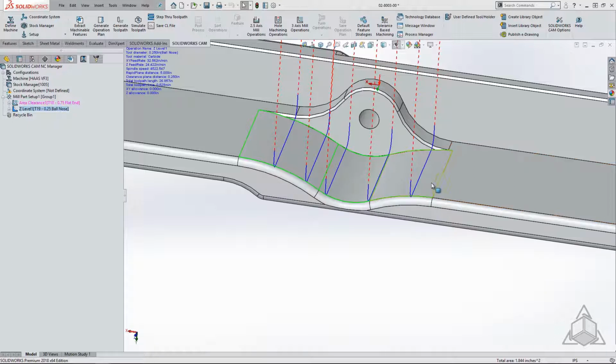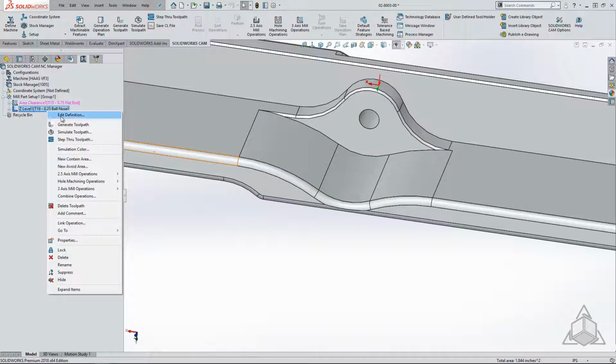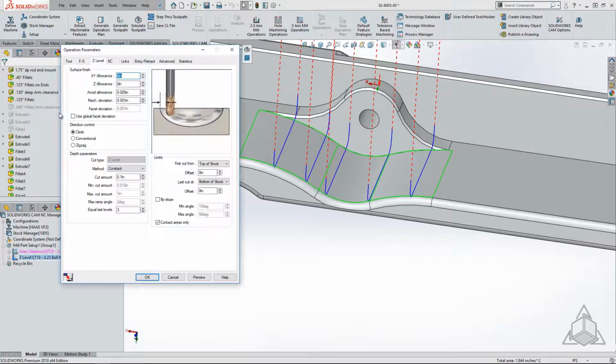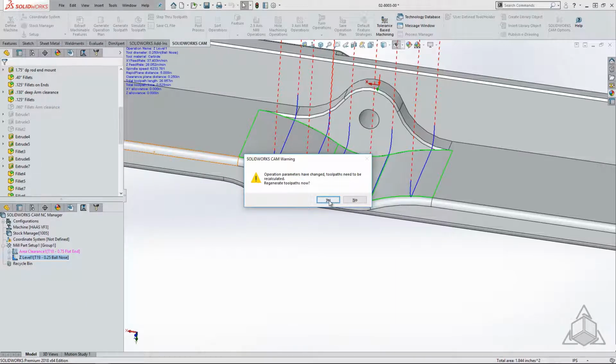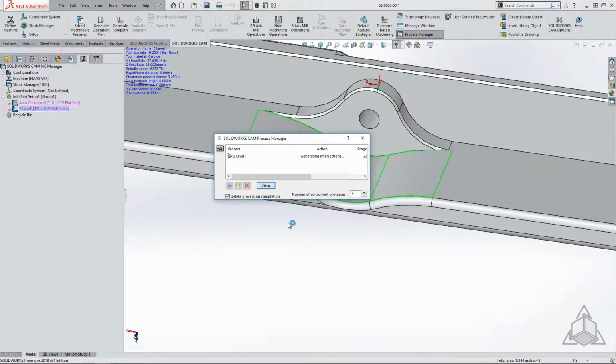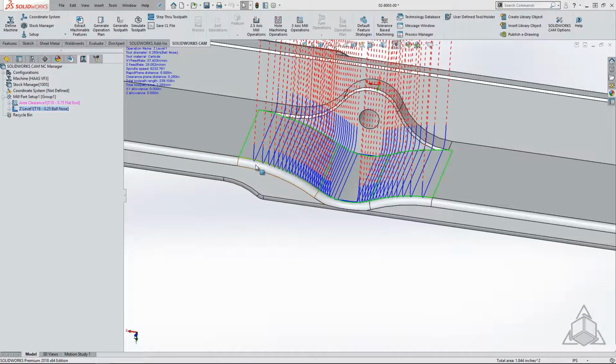So it can't come down and follow along this contour here. It actually has to go back and forth because it's not doing the full 3 axes at the same time. It's only doing your X and your Y, so it can't actually come down and go back over. So it is limited in this case, and our step over is defined not by a horizontal step over, it's actually defined by a vertical step over. So we're saying that our depths are going to be 0.01. So it's looking at the depth or depth change to determine where those Z levels are going to be.